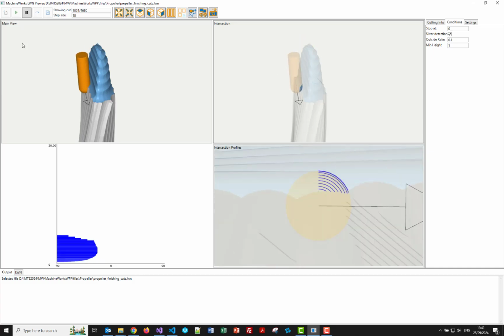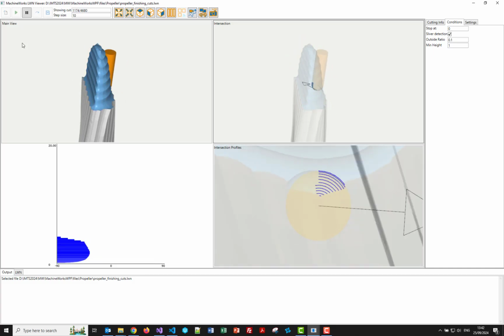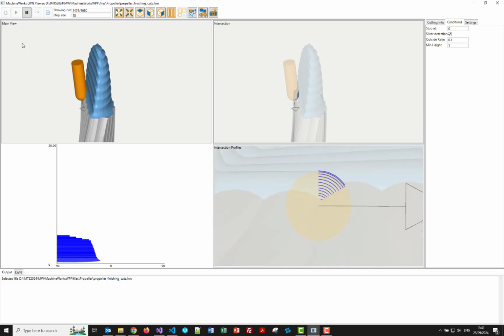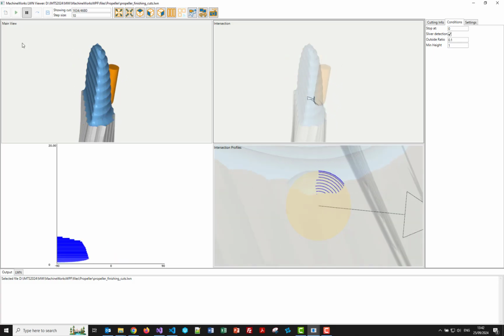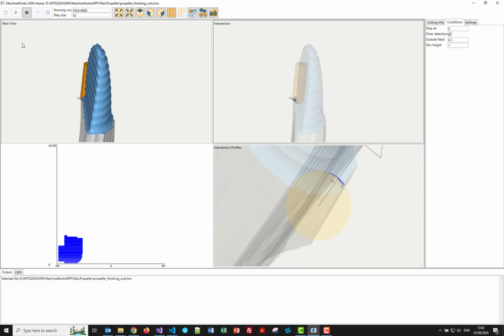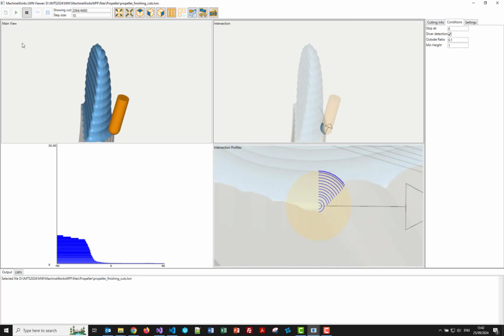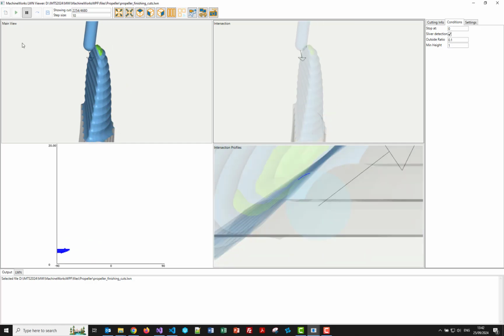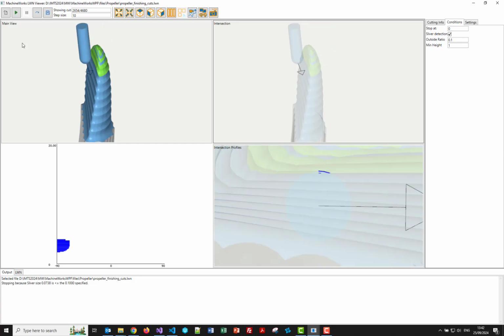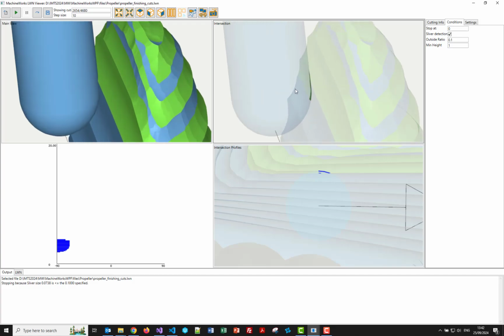If the thickness of the cut is less than about 1/10 of the radius of the tool, then stop, in effect call it a stopping condition, so that we can find a reasonably thin cut. So there aren't any in these finishing cuts, or in this first set of cuts, because it's removing quite a lot of material. But okay, here we go, it's found one here with these deliberately thin cuts.